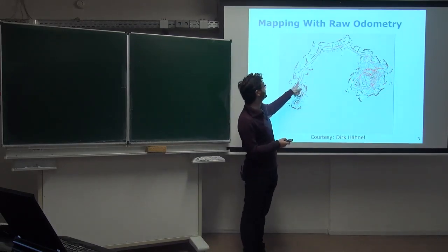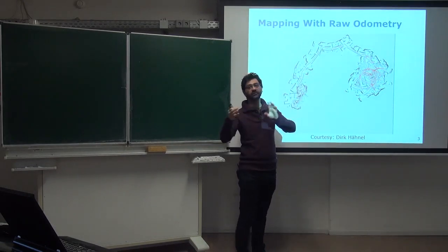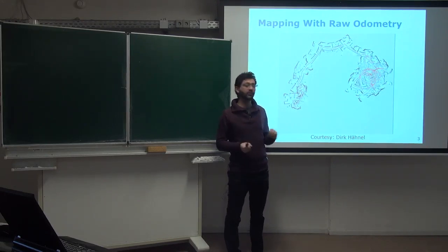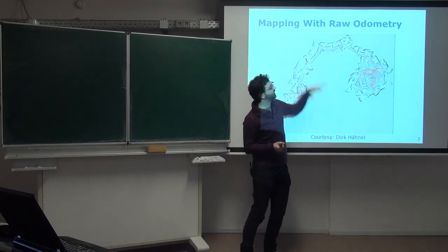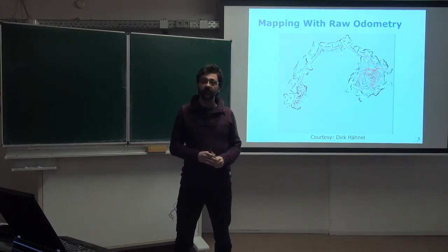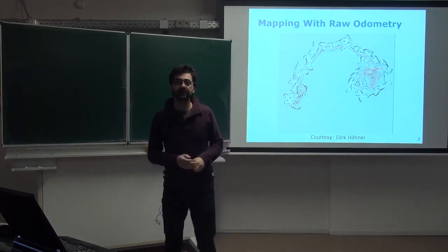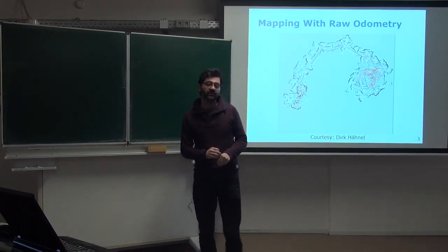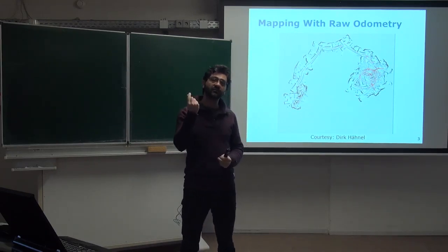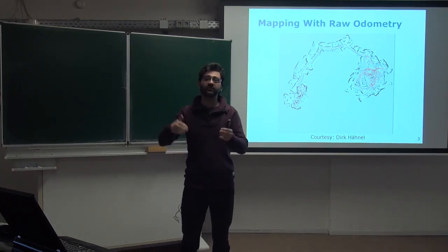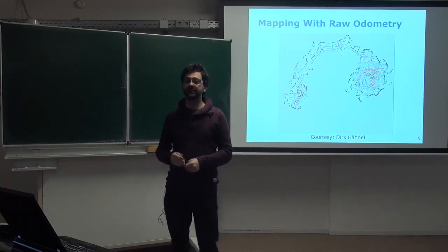Here you can see that the robot is actually trying to go straight, but there is a bias in the odometry. It can be that one wheel has less air, or is a bit unmounted or wrongly calibrated, and you see that it basically produces bended corridors and so on. These are typical errors you find in odometry. You can calibrate this and get slightly better results, you can have very good odometry and get better results again, but eventually a small error is always present. It's almost impossible to remove it. There can also be stones on the ground, so you have perfectly calibrated odometry, but it jumps on the stones and then slips and so on. So you will eventually get lost.